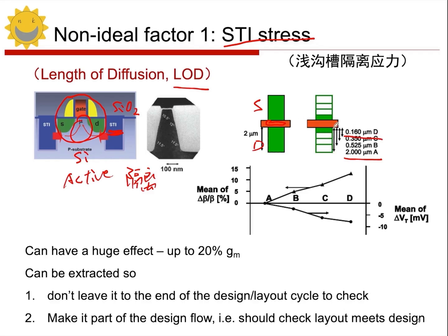Now note that the channel regions of these 4 transistors are completely identical, right? Their width to length ratios haven't changed at all. They all have the same aspect ratio. The only difference is the area of the source and drain. Specifically, this refers to the distance from the edge of the source and drain to the channel region. This distance changes from A to D, getting closer as we go from A to D.